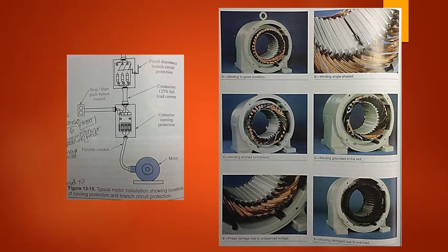The second form of protection is called run protection. Run protection protects the motor from excessive heat damage or fire while it is in a normal mode of operation. Run protection is a necessity since only a slight mechanical overload to a motor will, over a period of time, cause damage or fire.